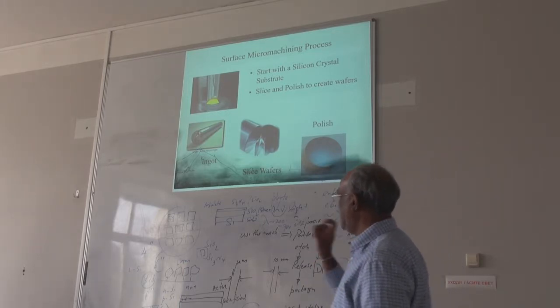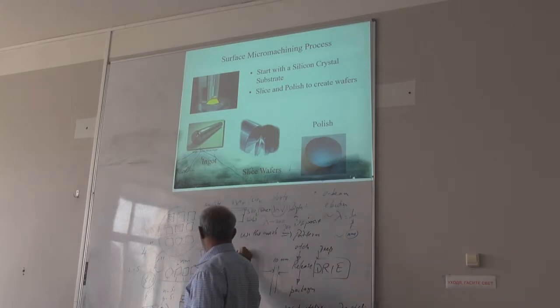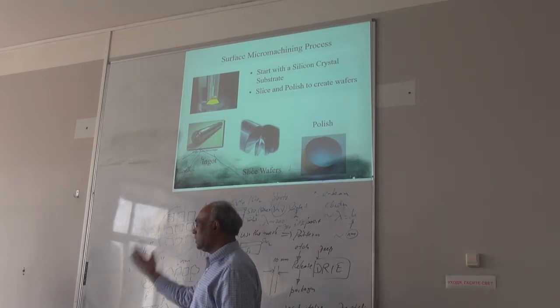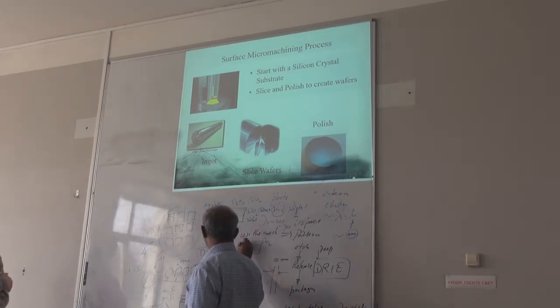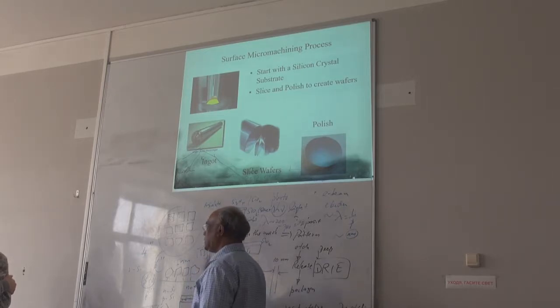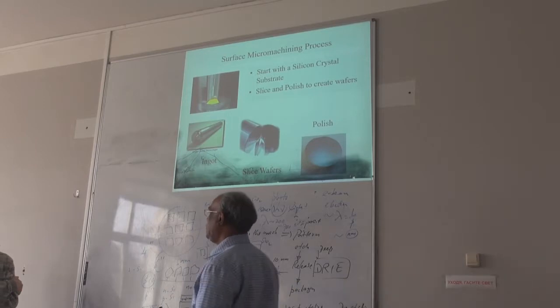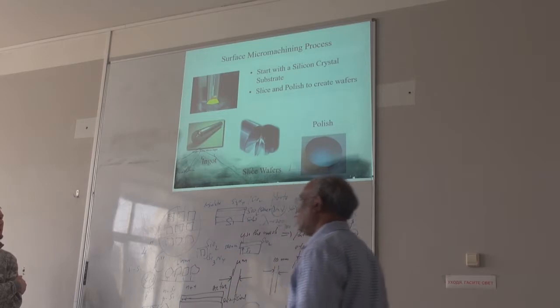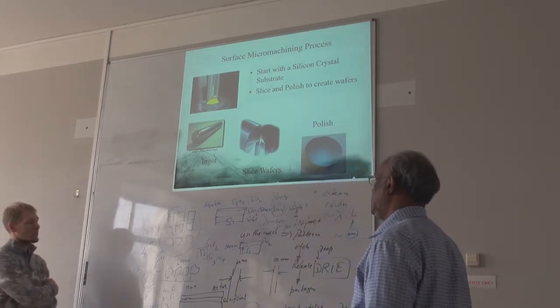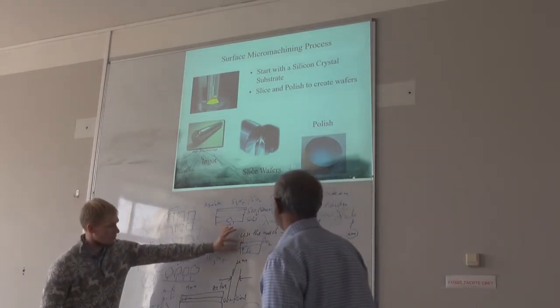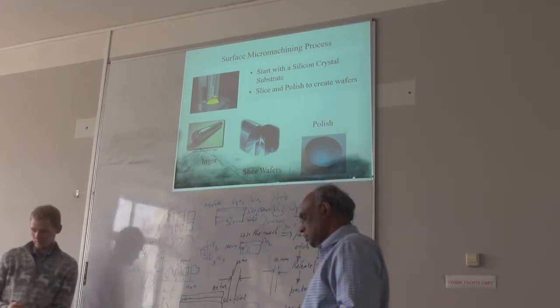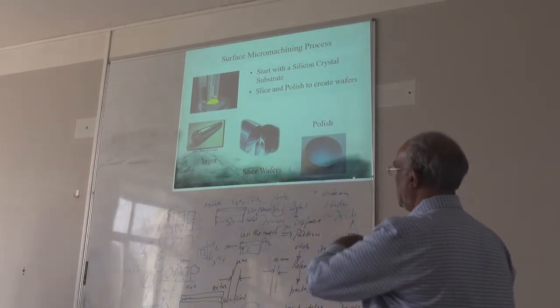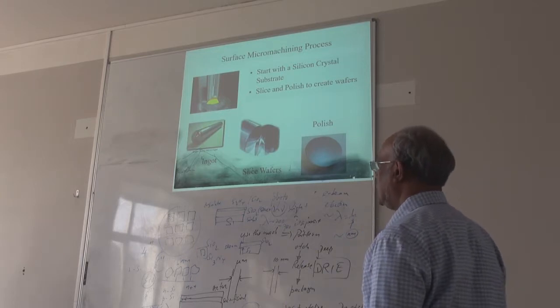But you have to define how much silicon dioxide you want. You can specify, say, 500 nanometers of oxide, but then it's a little expensive. We usually buy only the silicon wafer. We do oxidation in our clean room. You do oxidation? Yes. And you can control that thickness? Yes, we can control that. We only buy just silicon without oxide.